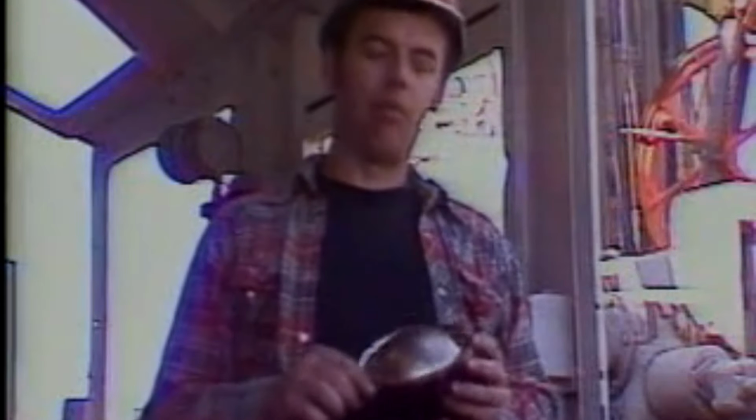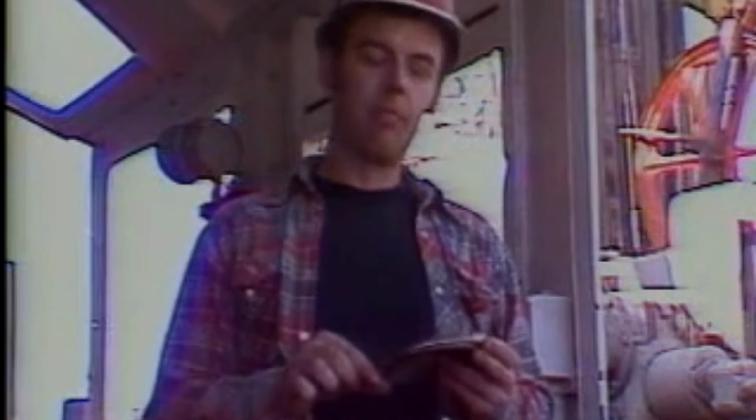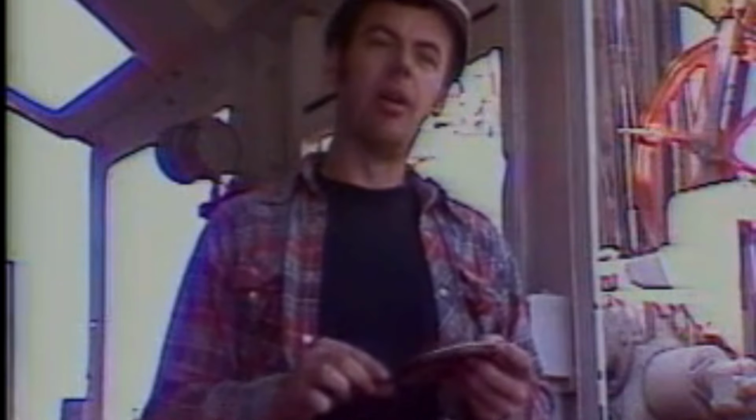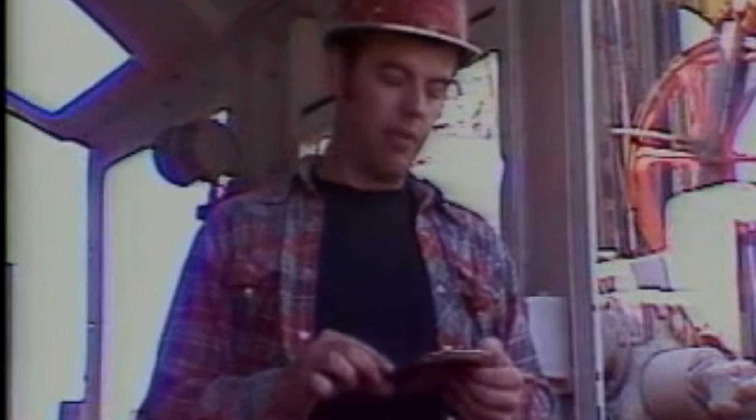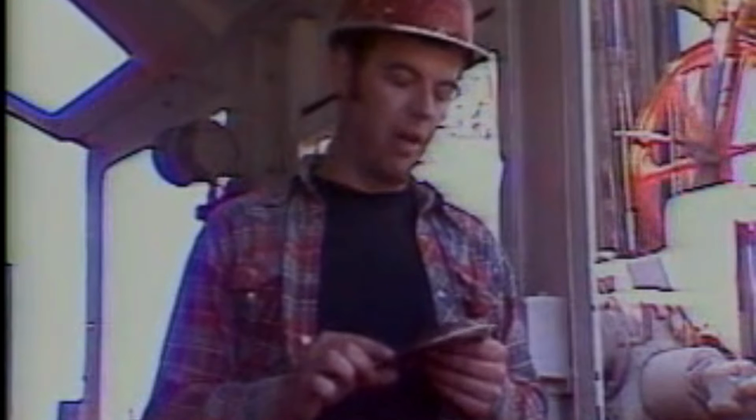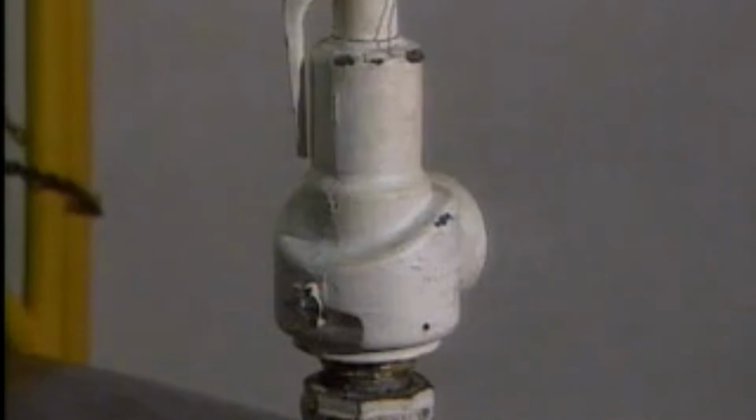This is a rupture disc. It is designed to rupture at 39 psi. In each of our 8 P tanks, we have one of these rupture discs inserted. So great care should be taken when allowing the flow of air to enter the P tank, for too much volume will cause this disc to rupture, and also over a prolonged period of time, too much pressure will result in the same. Some rigs use pressure relief cocks, but both serve the same purpose.